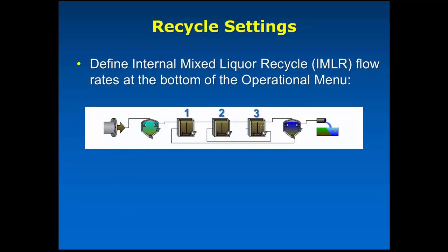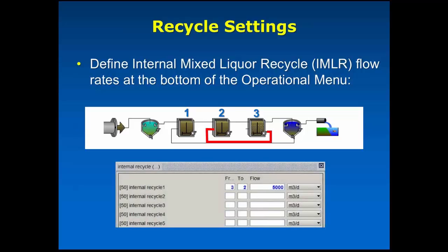And what it does is you specify by which zone or which number of reactor in series that you want to do. So let's pretend that we have something that looks like the example that I gave you before, where we have 3 tanks in series. And I'm going to do this with a plug flow tank instead. And I want to be able to put in this internal recycle. If I was doing it explicitly with the CSTRs like it's done here, you draw that internal recycle right on the board. However, in the plug flow tank, you don't even need to do that. It's much simpler to go to that internal recycles menu and pop it up.